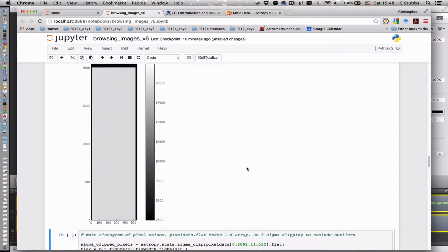So this is the way I'm accustomed to looking at amplifier images, where now the bottom left-hand corner contains the amplifier, the serial register runs in the horizontal direction, and the pixel flow is from the top, marching down with parallel transfers, and then out to the left with individual shifts in the serial register. And now we can see that the pre-scan is fewer pixels than we have in the overscan, and this is the overscan row region up here at the top above row number 2002, where phantom pixels are read out and stored in the array.